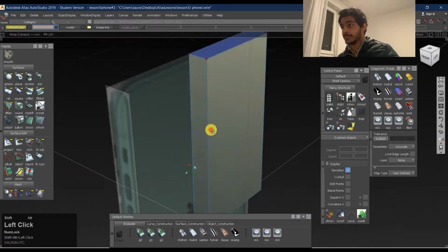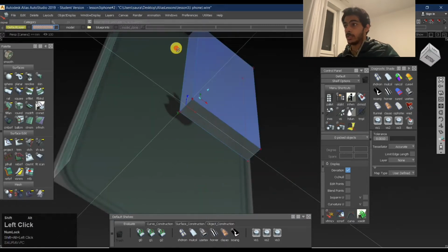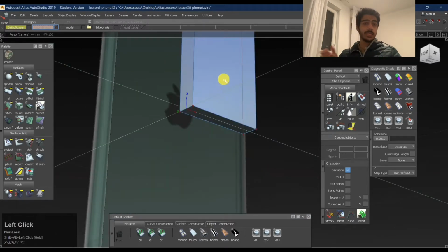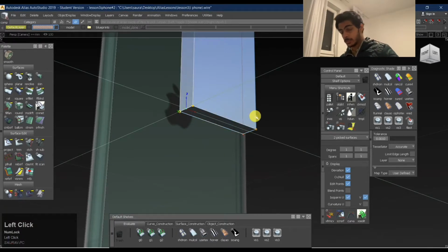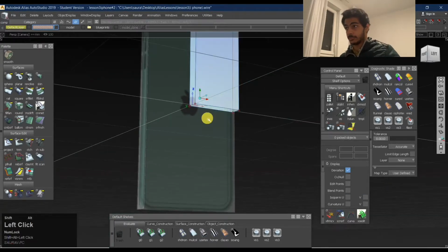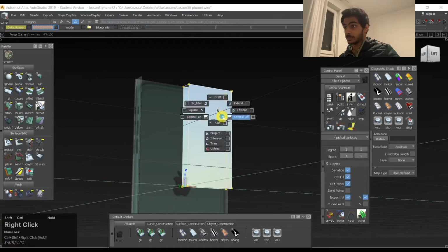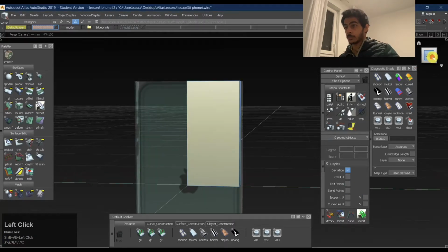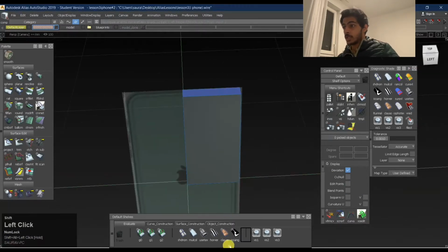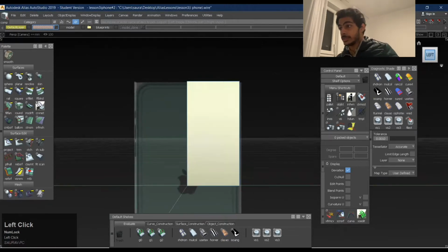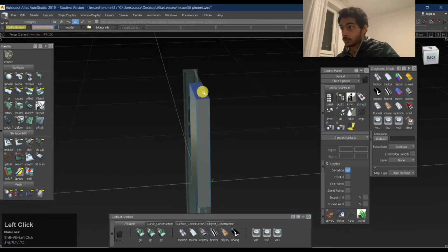Now there are surfaces on this part and this part as well, on the bottom as well. But since we know that it's going to reflect on both the sides, we need to get rid of them as well. So we'll just delete these surfaces. We'll pick these surfaces, we'll hide the control points. Now we have something like this, but we still don't want these two edges, right? We don't want these 2 surfaces.